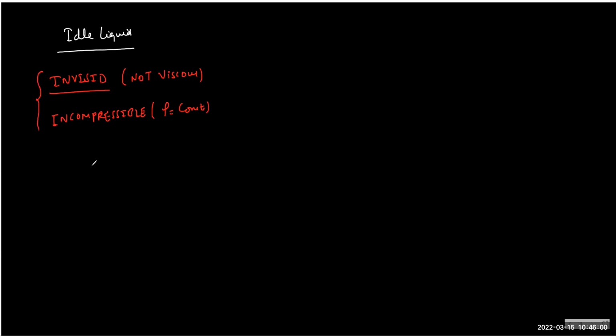And because in our case the liquid is inviscid, velocity will be the same across one given cross section. So we generally assume that one cross section will have one particular velocity. Every cross section will have its unique velocity, and if the cross sections are the same, velocity must be the same. So we look for the cross section area. In case of fluid flow, until we change the area, we cannot change the velocity. That's the idea: one particular cross section cannot have two separate velocities.